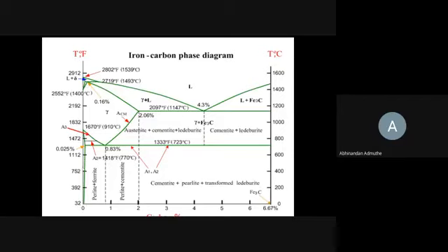And obviously these are solid solutions. This is not a substitutional solid solution, this is an interstitial type solid solution. Why interstitial type solid solution? Because the size of the carbon is less than 1 angstrom, and in combination with iron it forms an interstitial type solid solution. So you can see in this iron carbon phase diagram only 3 solid solutions exist, that is alpha ferrite, gamma iron and delta ferrite. And these are terminal solid solutions because these are close to one of the terminals of the phase diagram.